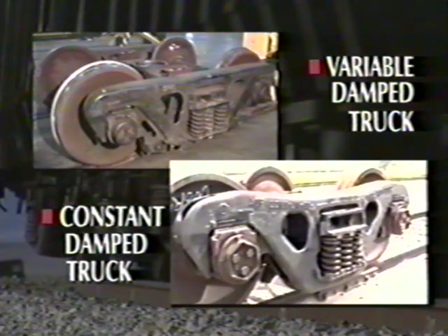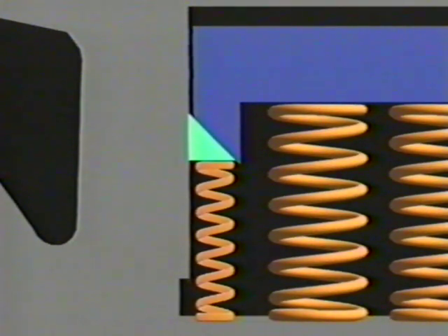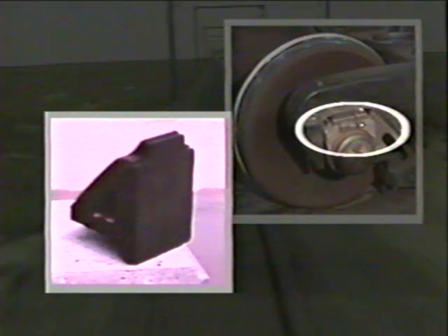Different truck designs have different warp resistances. Snubbing pressures on variable damp trucks elevate as a car load increases, which provides higher warp resistances. Snubbing pressures with constant damp trucks remain constant as the load increases. Some truck components can reduce the warp resistance when they are applied improperly. Elastomer-coated snubbing wedges and elastomer-bearing adapter pads are intended to be used on specific truck designs and should not be improperly applied. An unsuitable application of these devices could potentially lower a truck's warp resistance.